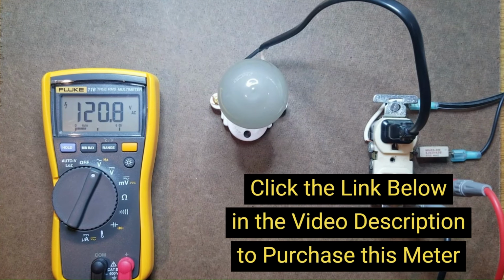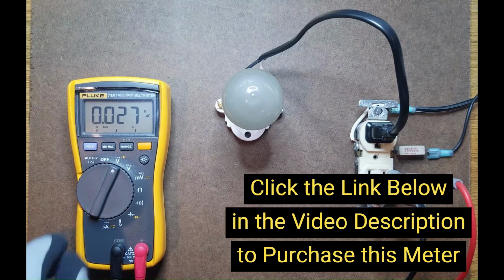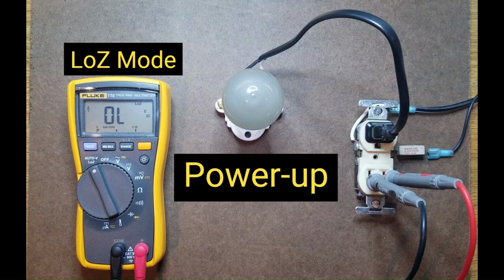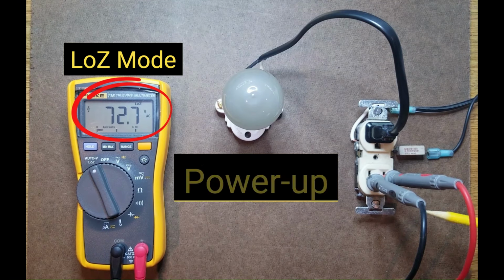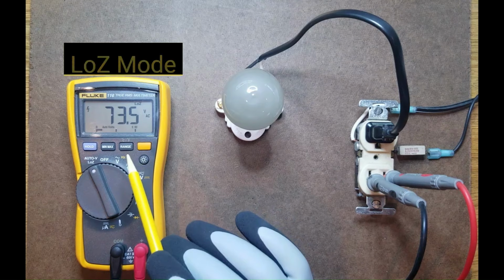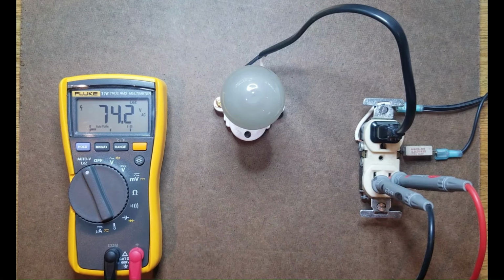Well, if you have a LoZ meter, I'm going to go ahead and turn this voltage off here. I'm going to put on LoZ mode. Now if I want to test this outlet, I'm only reading 71 volts. A regular 120 volt outlet should have no problem supplying 120 volts to a LoZ meter, and the LoZ meter should not affect it, not even perceptibly at all.